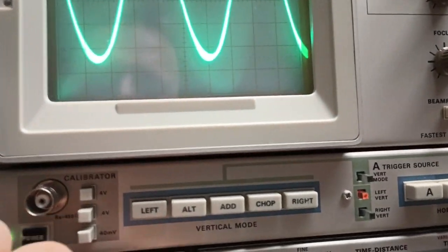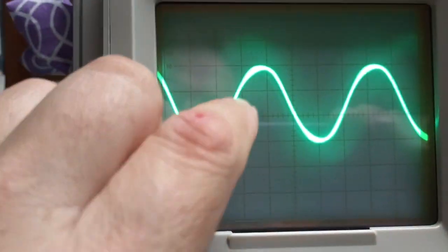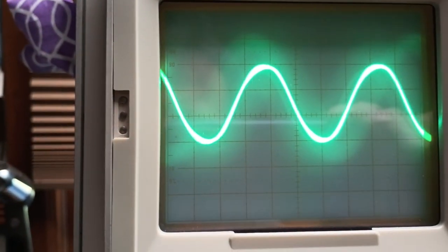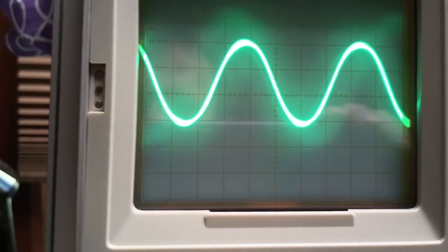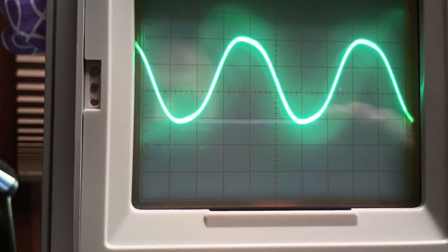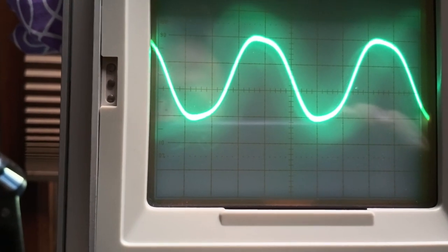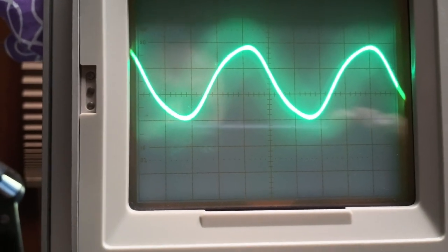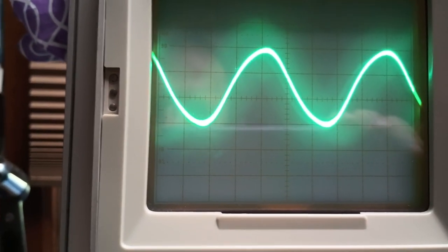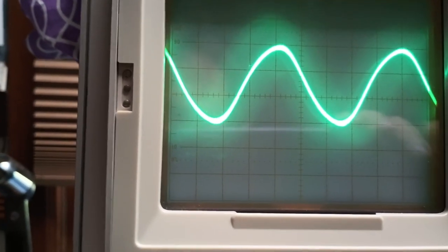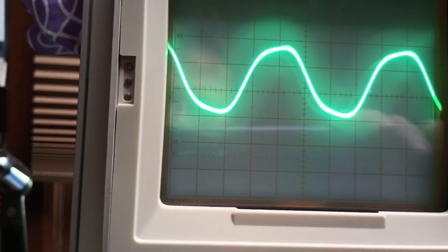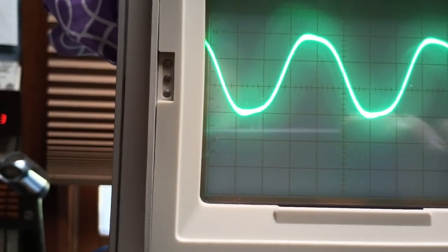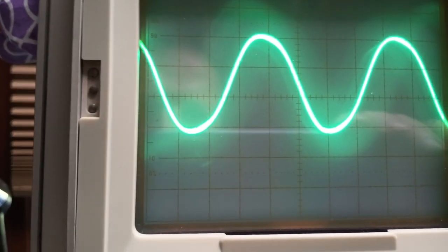So this display says about the same thing as the amplitude of the generator, which is about 3 volts peak to peak, at half a volt peak to peak at 1 volt, 1, 2, 3, well, that kind of implies that antenna might be pretty well matched. You see the amplitude holds pretty steady down to 21.1. It starts dropping off. This antenna drops off fairly quickly at lower frequencies. Now there at 20.3 it picks back up again. But this is indicating what appears to be a resistive mismatch.